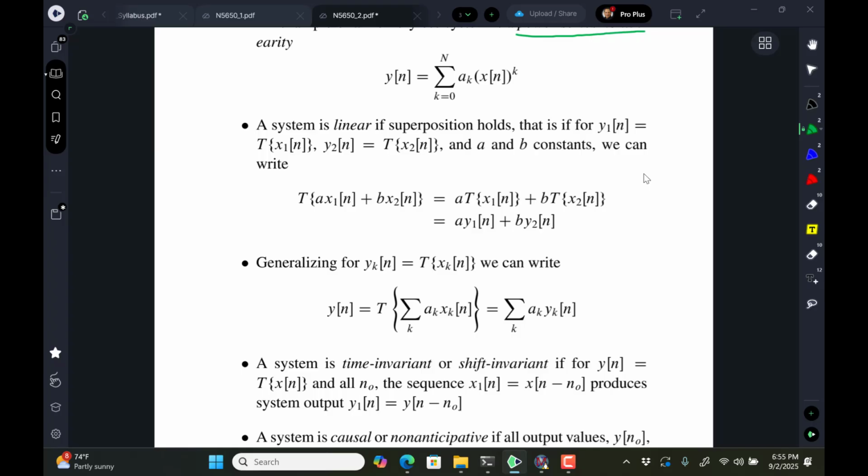To me, kind of a classic example, and I use this in the Dummies book, is the karaoke machine. What does the karaoke machine do? There's music that was pre-recorded that plays, and then the singer comes up with a microphone and sings into it, and the two things are playing out together. That is the ideal linear system. If the singer gets too excited and sings really loudly, they'll distort the amplifier because they'll overdrive it, and then the system is no longer linear, so the output is not the sum of the two inputs with some scale factor. It'll be a distorted version of it.